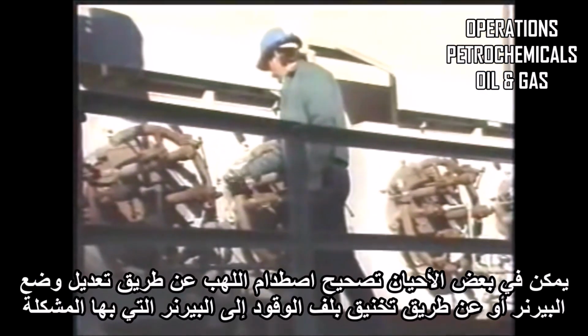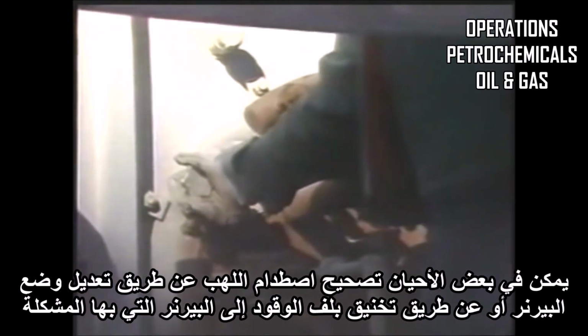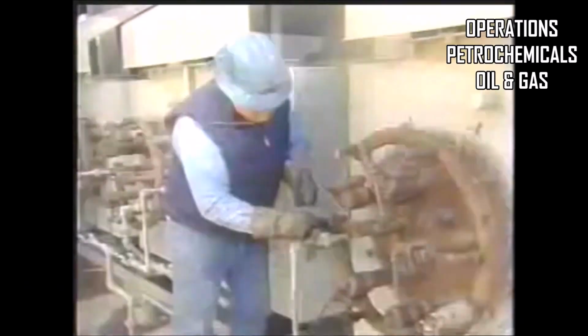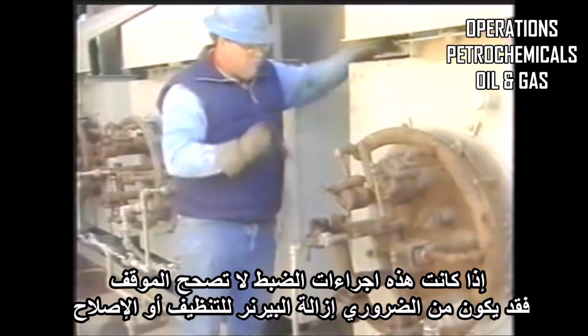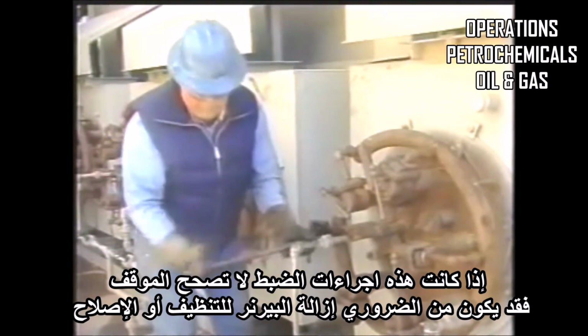Flame impingement occurs when the flames are actually touching the metal surfaces inside the furnace, usually the tubes. This contact weakens the metal and can quickly plug up a tube with coke deposits. Flame impingement can sometimes be corrected by adjusting the position of a burner or by pinching back the fuel supply to the problem burner. If these adjustments don't correct the situation, it may be necessary to remove the burner for